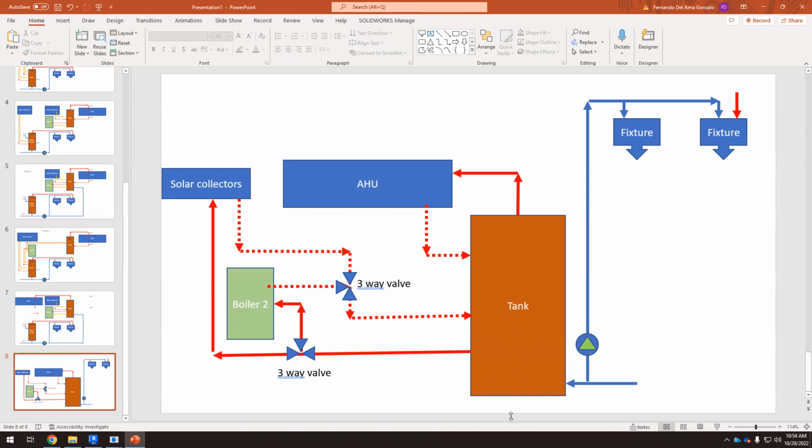Okay, so the water supply comes at a pressure. Remember that it was 60 pounds per square inch. So when we have 1 floor, 2 floors, or up to 3 floors, probably the pressure that comes from the municipality is enough. But if there is some issue with the pressure that comes from the city, we need our own water pump to move the water up. Okay, but that's all we need.